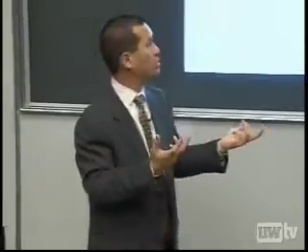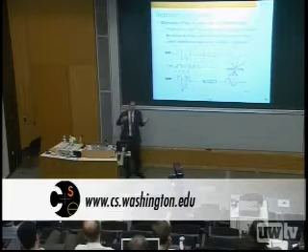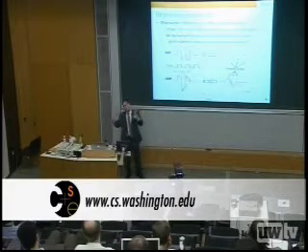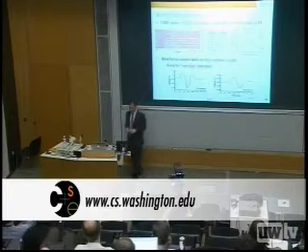If I don't have changing bits, then I don't have double the preemphasis, but I didn't need it because, well, it's a hysteretic receiver, and I don't need to actually have twice the preemphasis. So if you sort of squint hard enough, you can call this adaptive preemphasis. That's a bit of a glorified term, but we built this chip and showed it at ISSCC this year.